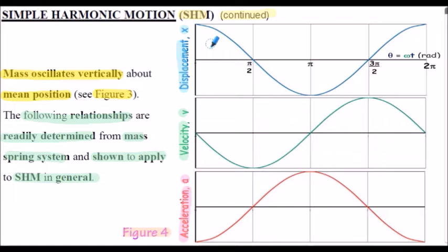So for initial displacement x of the mass from the equilibrium position, we initially will have zero velocity because it's commencing from rest, the extreme x distance from the equilibrium position, and on release of the mass, due to the spring stiffness effects, there will be an inward acceleration generated. The mass then oscillates with the variation in displacement as shown by the top diagram, essentially a cosine curve.